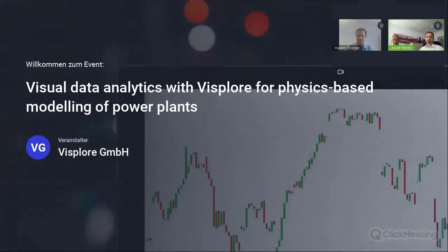By nature, there is degradation from fouling, there is dust that accumulates, there's erosion with the equipment. So there is always some slope with the degradation lines, with the KPI lines. But the moment that they become too steep, or the moment there is a step, that should trigger an alarm, and that can be automated as well.